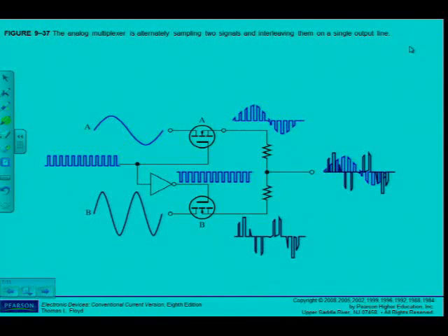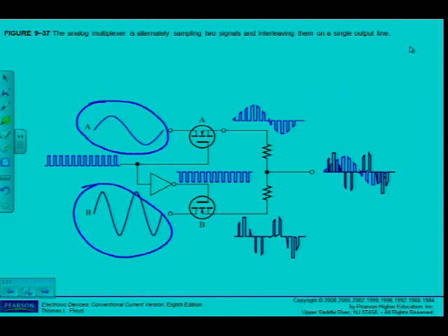So if we go and look at that circuit, I can see here different colors, although not that clear on the board. There's my A, there's my B applied, but see what happens here is this pulse signal that's applied here at the gates without an inverter to MOSFET A, but via an inverter to B. So the inverter inverts that pulse signal.